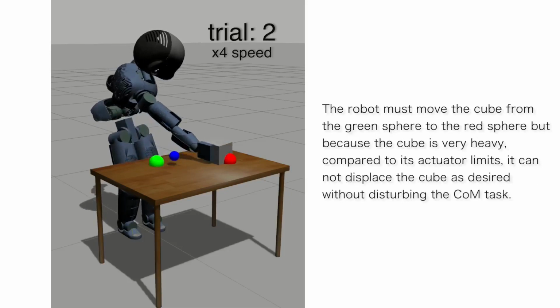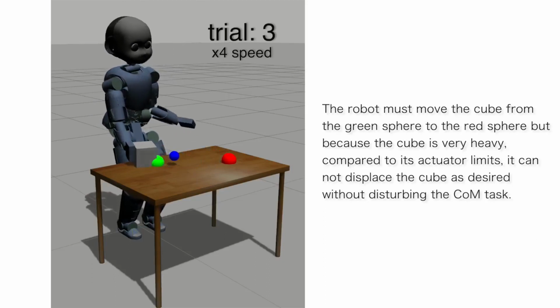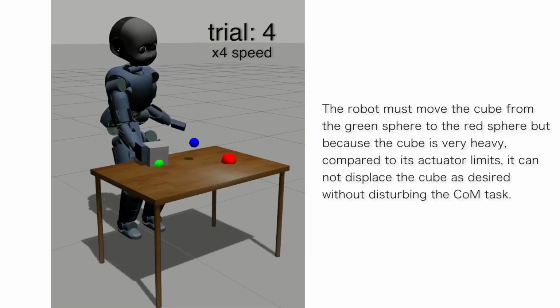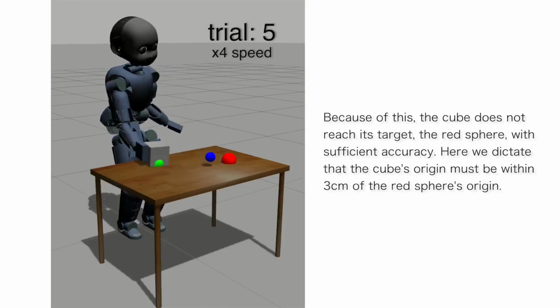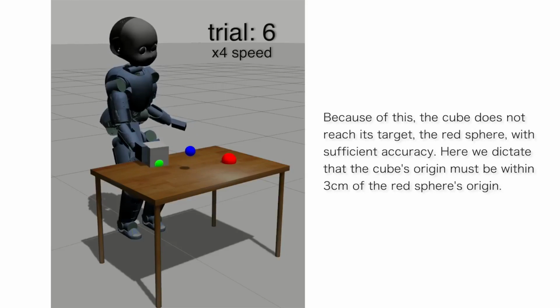The robot must move the cube from the green sphere to the red sphere, but because the cube is very heavy compared to its actuator limits, it cannot displace the cube as desired without disturbing the COM task. Because of this, the cube does not reach the target, the red sphere, with sufficient accuracy. Here we dictate that the cube's origin must be within 3 centimeters of the red sphere's origin.